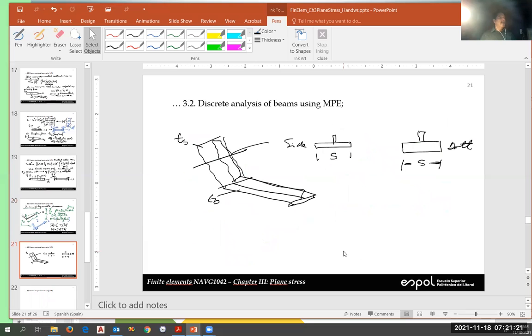This is something that somebody asked this morning. When we have this case, we have this frame, and this frame is welded to the plate. So in order to have the inertia, we have to consider both the plate and the stiffener. For example, if we had an angle here, we should include all of this in order to calculate the inertia.